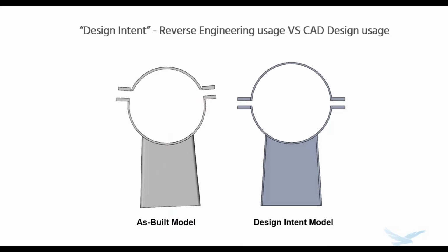Another thing to be aware of is what we mean by design intent. I realize a lot of you are SolidWorks users, and if you've taken a SolidWorks Essentials class or learned it in school, this is one of the first concepts you hear. They're basically referring to the practice of thinking ahead, just like you would in a chess game, and thinking about how the moves you make now are going to affect what you're able to do later on and how you do it. Parametric CAD models consist of a bunch of interdependent features stacked on top of each other, so you need to approach the modeling in a deliberate, thought-out way that's going to result in the model being highly stable and highly editable downstream.